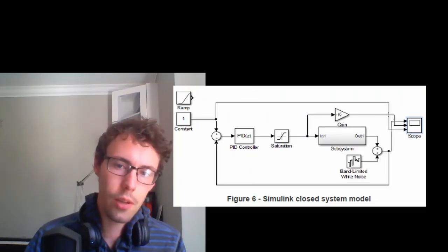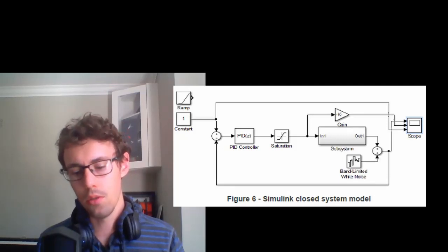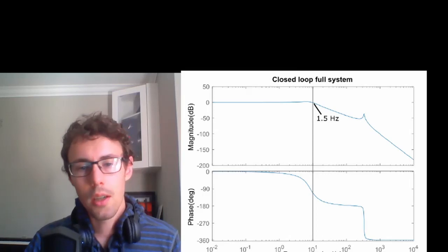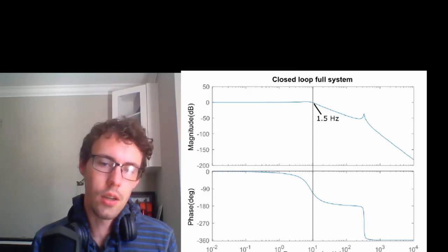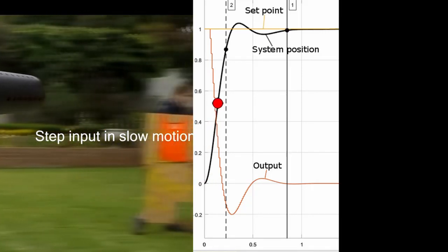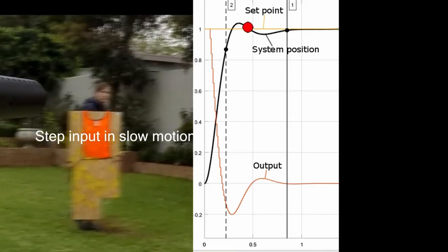So you build the Simulink model in MATLAB using the state space model, and you plug in a PID controller, then you start tuning it till you get to the steady state error you want. You want to have as little overshoot as possible, but be able to get to its target position in time. And then after I had the tuned values, I can start coding the controller on the microcontroller based on the algorithm I developed on MATLAB.